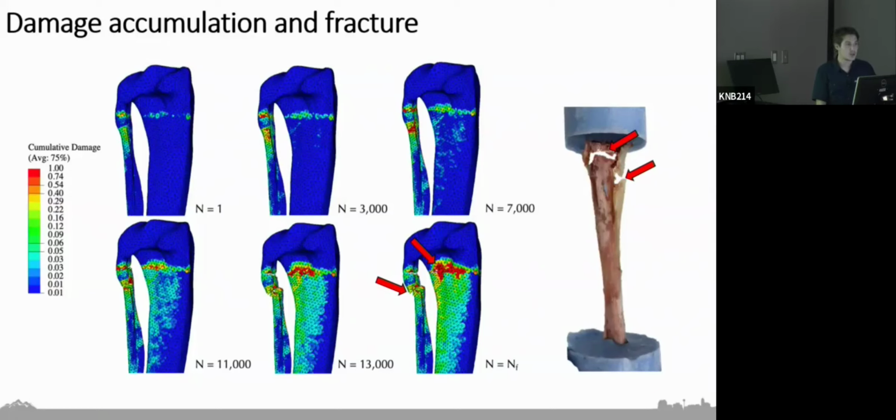In the damage model, the parameters that have actual meaning are the one VC strain and the time step parameter, and then A and B are just scaling factors to change the shape, like how quickly that damage accumulates. In the material model it's kind of the same thing. So A and B don't really have any significance. It's just how we get that optimal exponential relationship between density and elastic modulus.